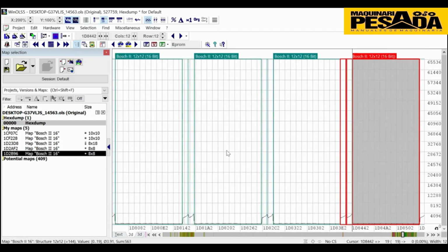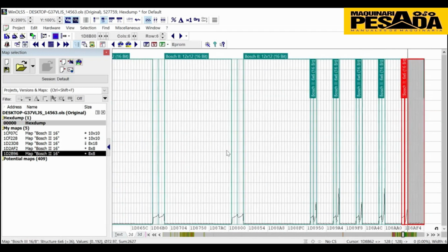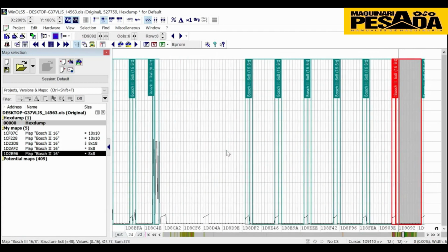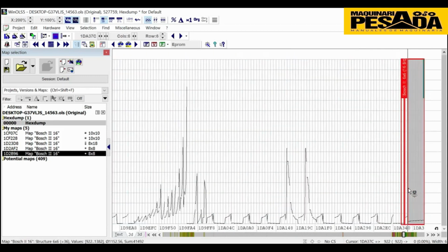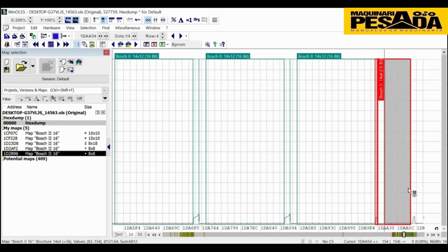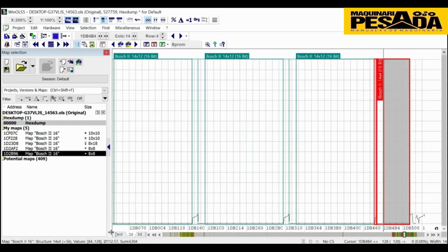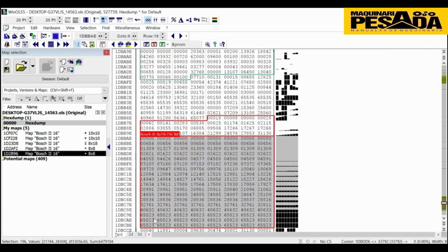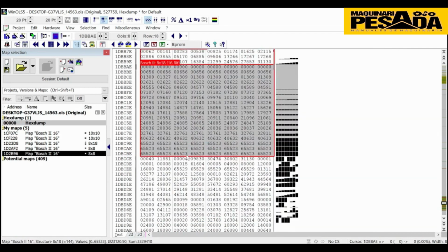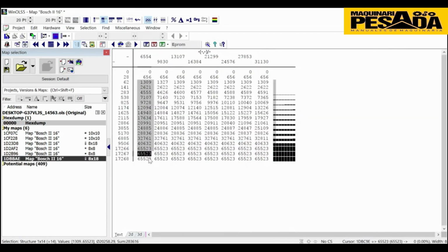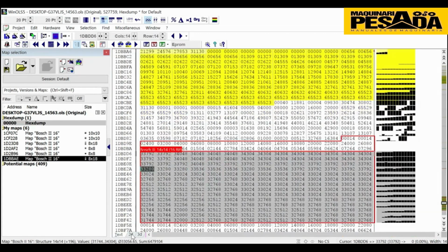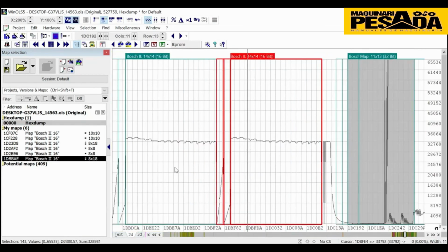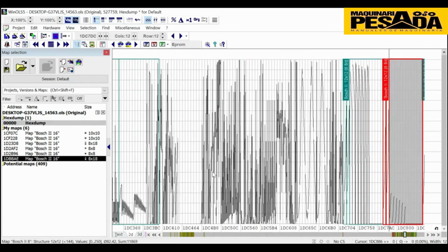Then I search to see if I can find new maps. For example, I need to find something like requested engine load, torque, optimal engine torque. You can even search in the 2D in the text view. There is no problem, okay? And this is going to be a throttle valve operating angle based on air mass. Look, it has this 2D view. These maps are injection correction. No need to touch them in stage 1 tuning.